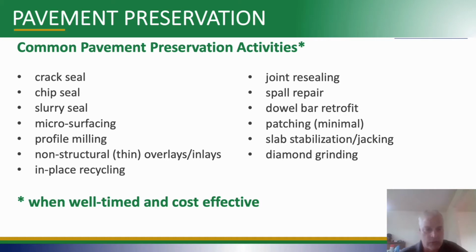So I don't need to read every one of them, but you can see that it's asphalt pavement treatments that are on the left and concrete treatments that are on the right. And again, all of these are considered preservation if they're done at the right time and cost effectively, and they will extend your pavement life longer at a lower life cycle cost.